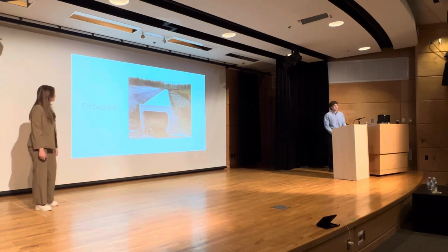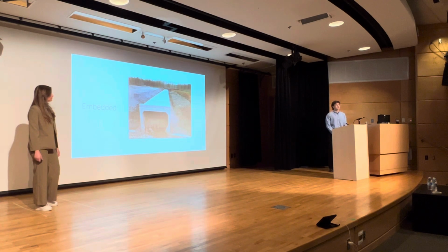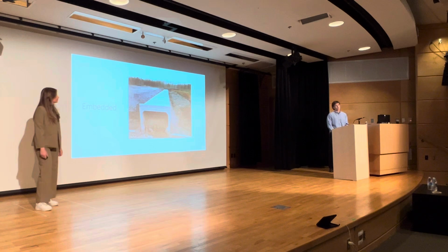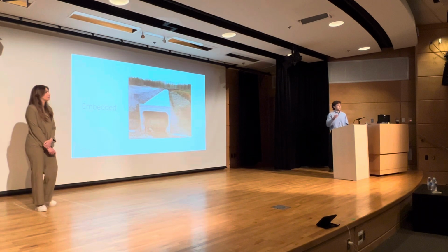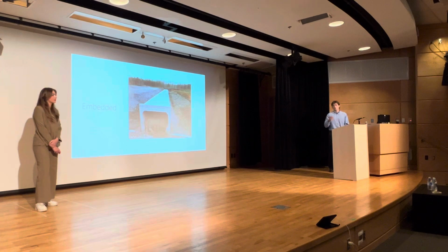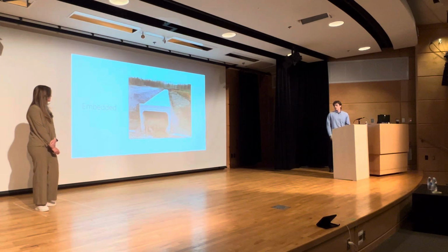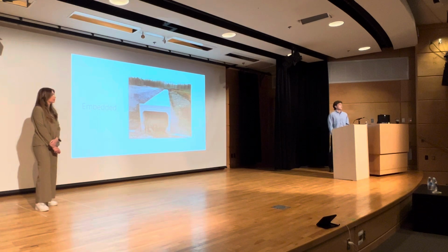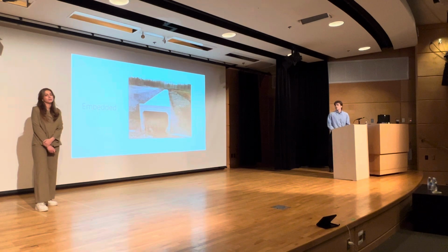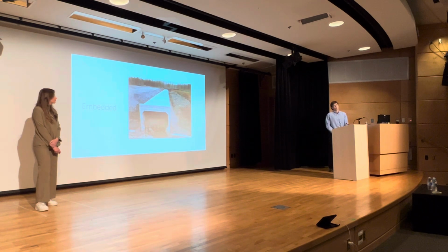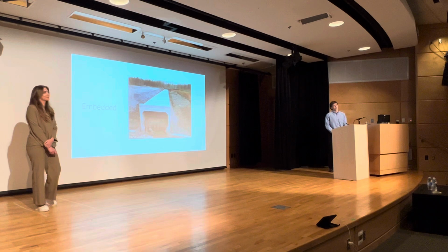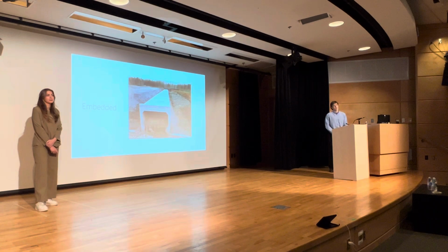Once velocities pick up higher than design velocities within the culvert, it can transport the soils from the high points to the low points, which will smoothen out the soils within the culvert, which will increase velocities inside the culvert, making it harder for fish to migrate through. Another thing for embedded culverts is that they are embedded to 40% of their total design width, which means that they lose a lot of cross-sectional area for the design flow calculations.